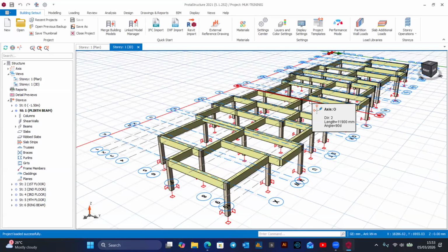Yes, I have noticed that most of you have been creating structural elements at the foundation level, story 0. Now, when you create beams in the foundation level, they are taken to be foundation beams. So if you try to copy them to other levels, you can't translate foundation beams into floor beams. The software cannot recognize it. So when you are starting your project, every element that you are going to start with to create should be created in story 1.